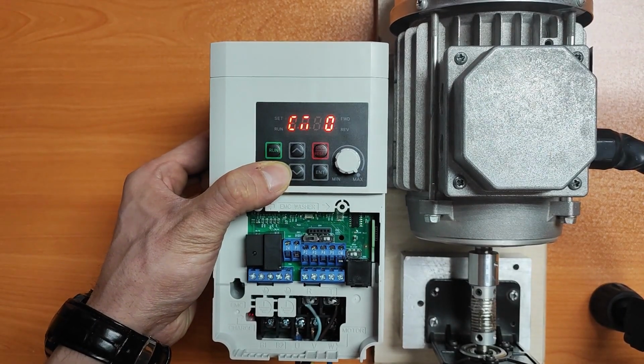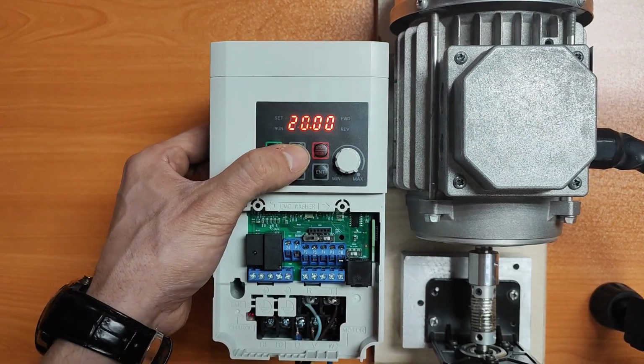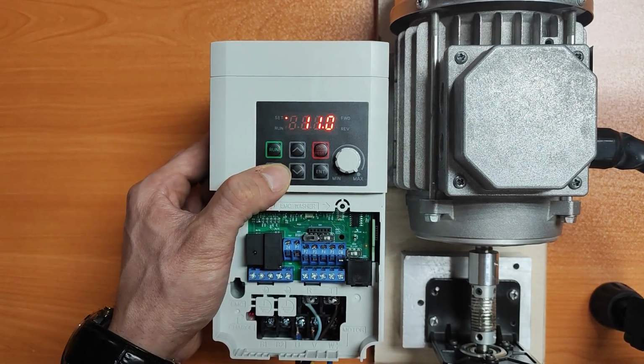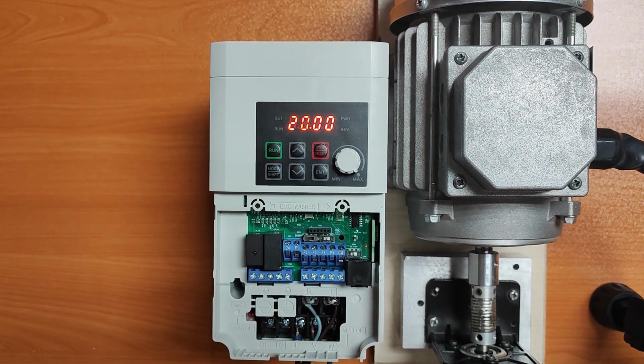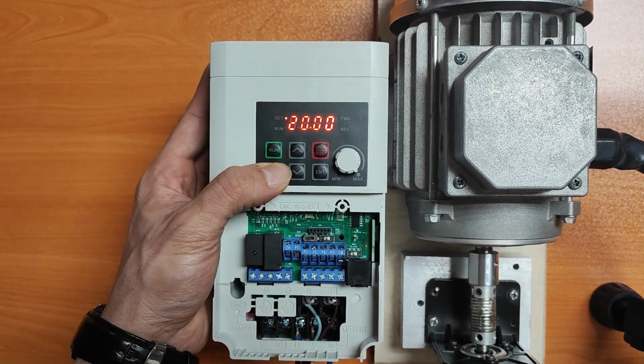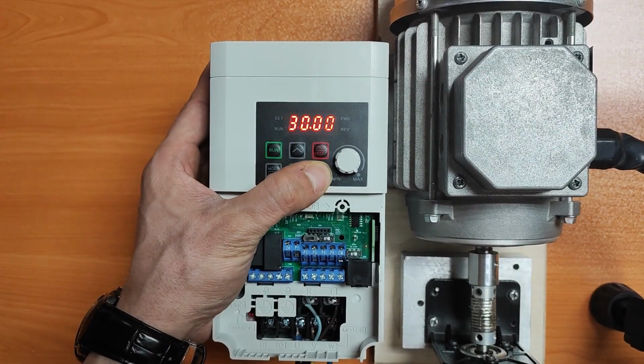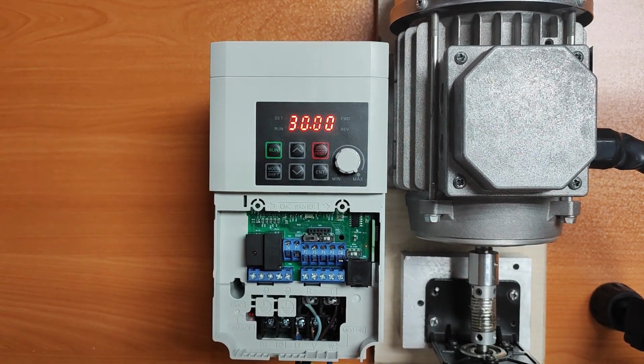But where do we specify our deceleration time? In the main group, in the DEC parameter. Now, for example, I'll set it to 10 seconds. It scales these 10 seconds between the frequency of 60 and 0 Hertz. Now, if I give a command frequency at 30 and stop the inverter at 30 Hertz, since my maximum frequency is 60, it'll go from 30 Hz to 0 Hz in 5 seconds. Because it had to go from the maximum frequency of 60 Hz to 0 Hz in 10 seconds. Since my frequency is halved, it must go from 30 Hz to 0 in 5 seconds.